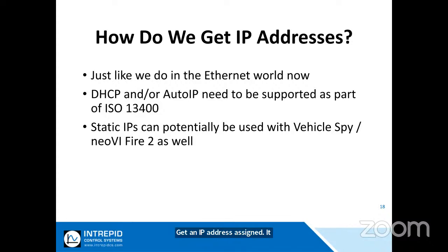It is also possible to have static IPs. The spec looks a lot at how to resolve and get your IP addresses for DHCP or auto IP. But I can tell you already, I've run into certain situations where the static IP for each individual car is set and unique, so that way they can still talk to many cars at one time. But keep in mind, DHCP and auto IP take time. And usually time is not on our side when we're manufacturing, and certainly not on our side when we're actually operating a vehicle. We need things in a very timely manner.